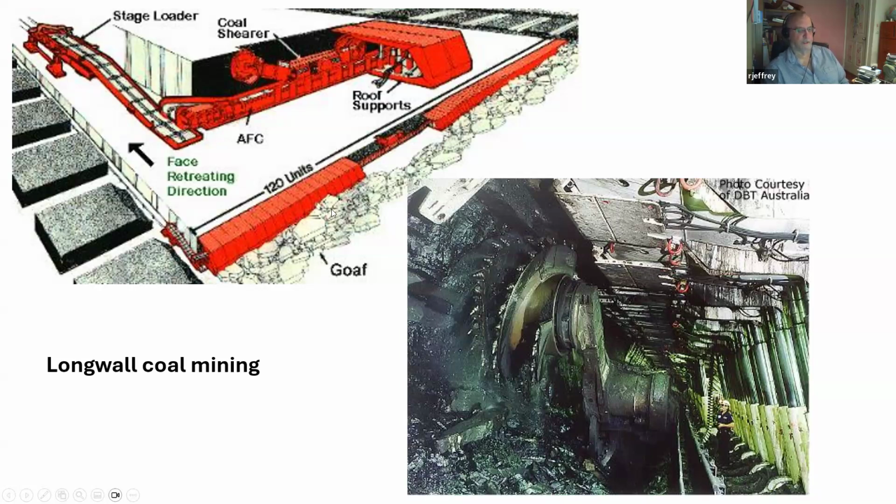So the issue that hydraulic fracturing addresses is that if the strata has a strong roof rock immediately above the coal, that is especially the worst condition when it's immediately above. And if that roof is strong enough, it can stand up for considerable distance as it's undermined. So instead of caving immediately after the supports, as shown in this diagram, it may stand up and leave a void underneath it.